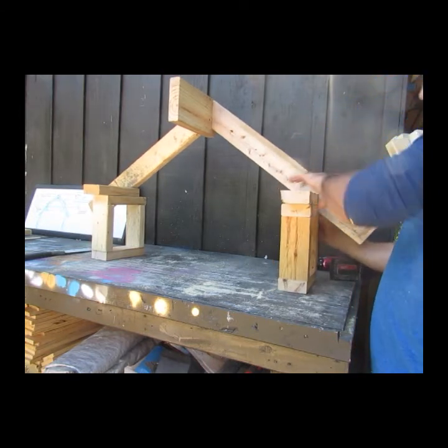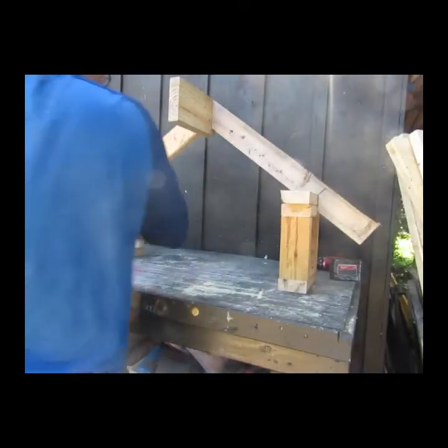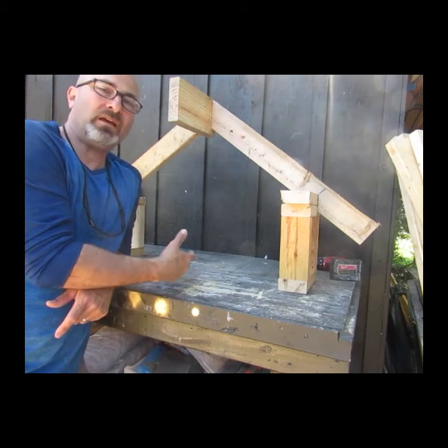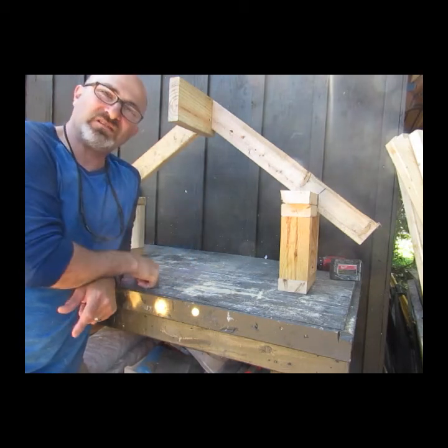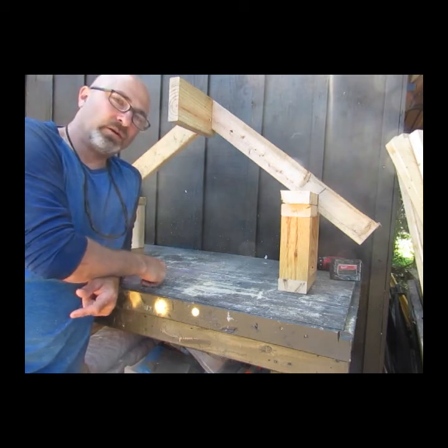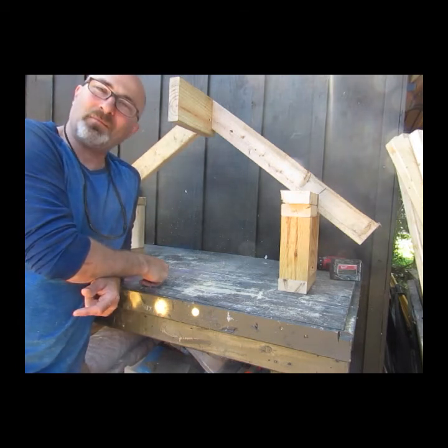And two. Now, you may be asking yourself, one screw to hold it in place? In real life, it won't be a screw. It will be a galvanized nail, an Ardox twisted nail. They don't spin out. They don't pull out. Once those Ardox go in, they stay in there. They're a nightmare to pull out.